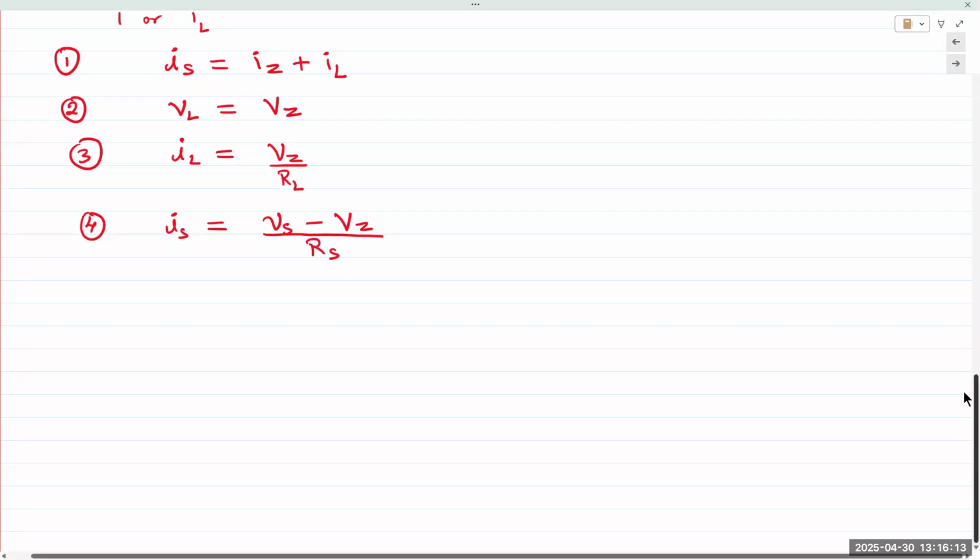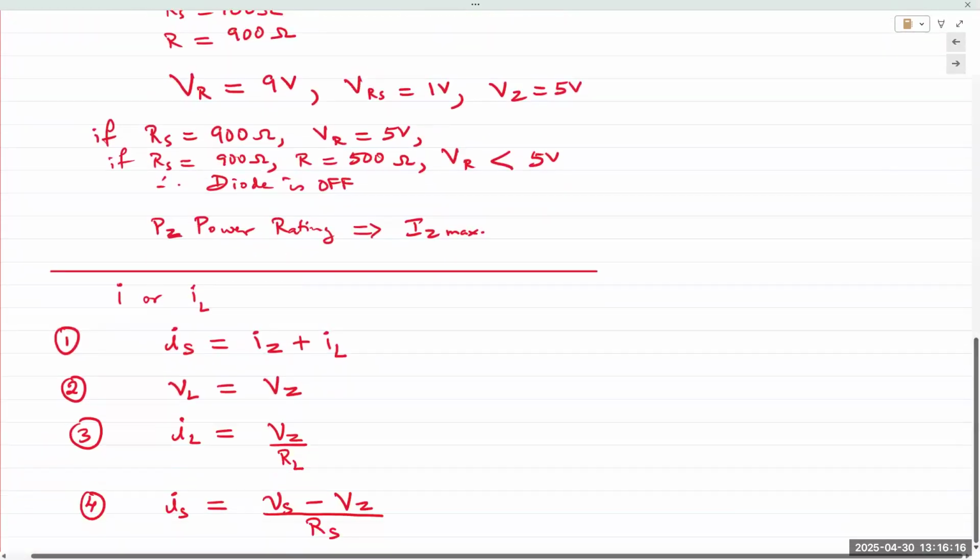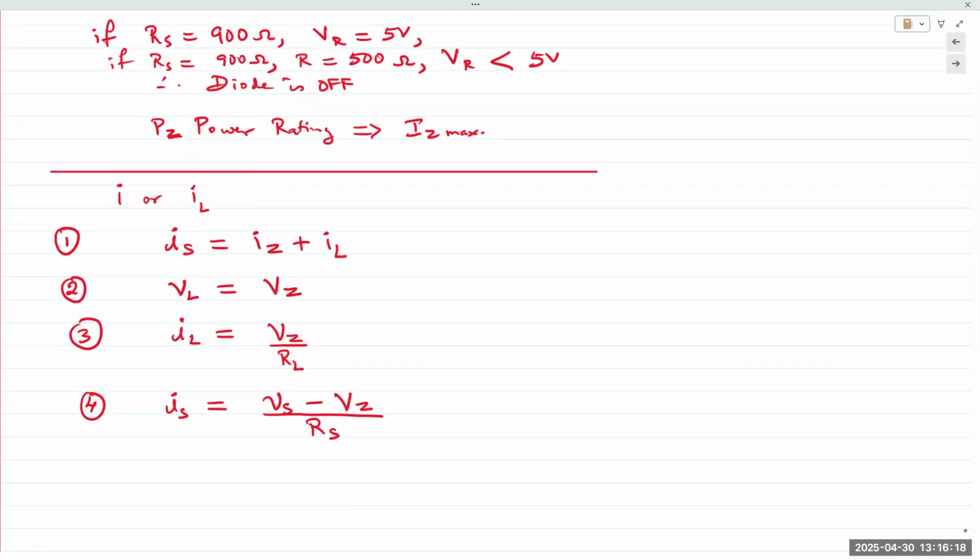Okay, so based on these conditions and these setup rules, if you're designing a practical regulator circuit using a simple Zener diode, then there is a limit on the supply voltage, meaning there's a minimum supply voltage that the circuit can handle, and there's a maximum supply voltage, as well as minimum and maximum values for the load resistance. And to take it even one step further, there's also a value for the series resistance RS. Again, you can see how all of those are interlinked.